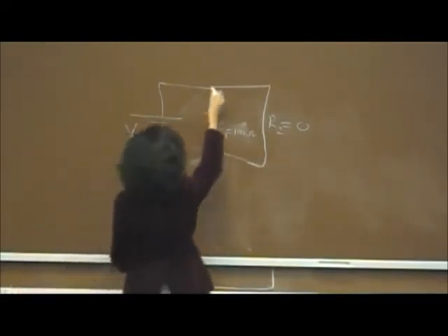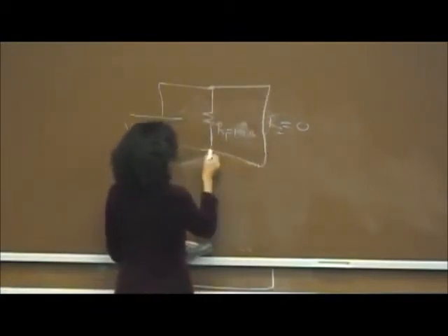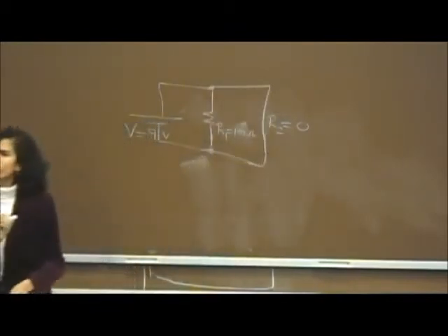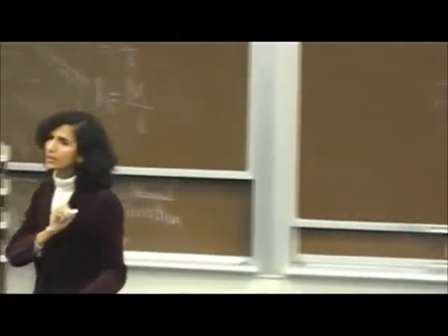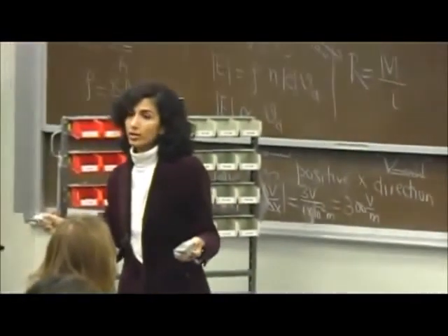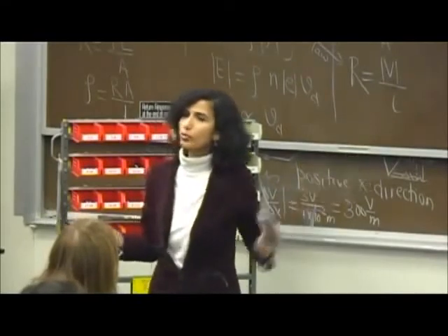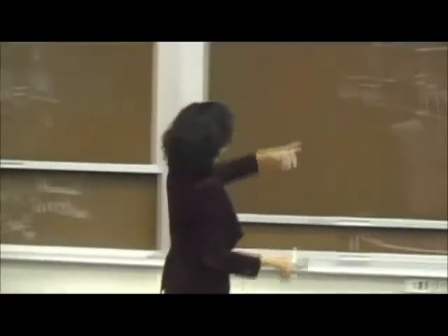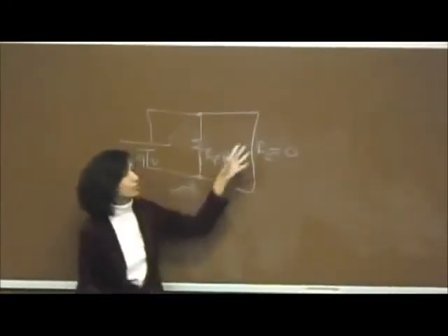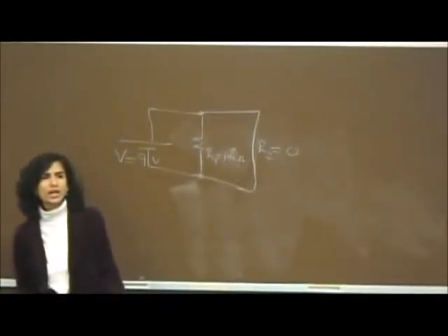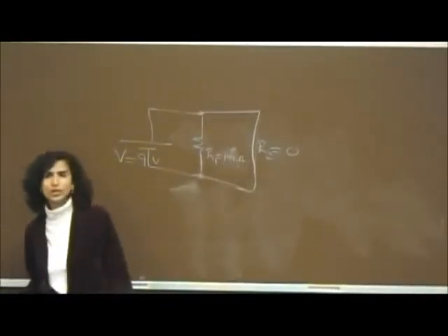What am I doing? If I'm just connecting a copper wire from here to here, between these 2 points, do you know what in common language it's called? Shorting, or short circuiting, right? Am I not shorting those 2 points? I'm just connecting a copper wire from here to here, there is no resistance in that part of the circuit. Do you know what will happen in this situation?